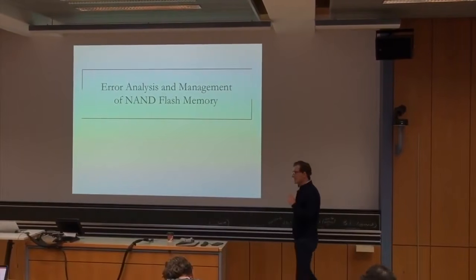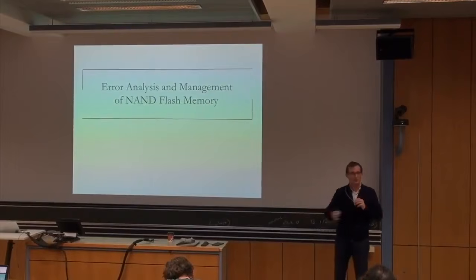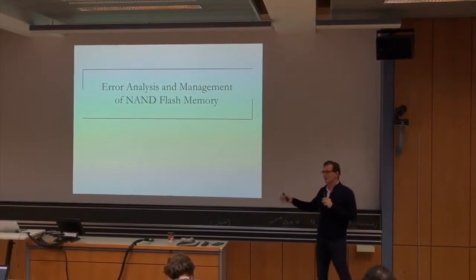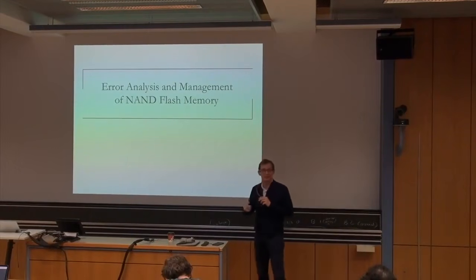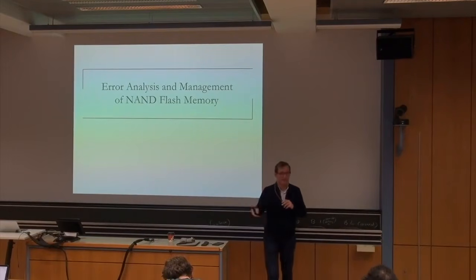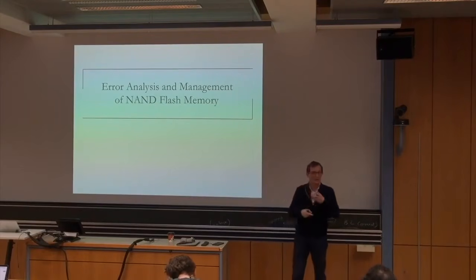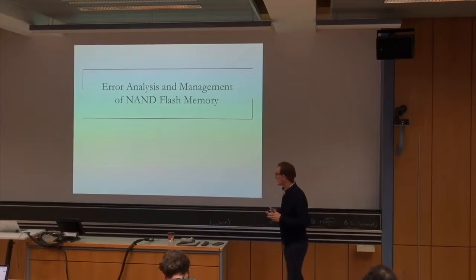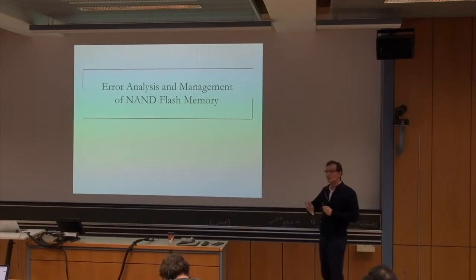By the way, I talk about erases, but these erases take a huge amount of time. So they take 10 to 100 times longer than a read. So scheduling is another issue that we're not going to talk about, for example. How do you schedule these requests? Because you have read requests, you have erase requests, you have refresh requests, as we will talk about. How do you schedule all of these requests to flash memory becomes interesting. Ideally, you would like these erases to happen in the background.